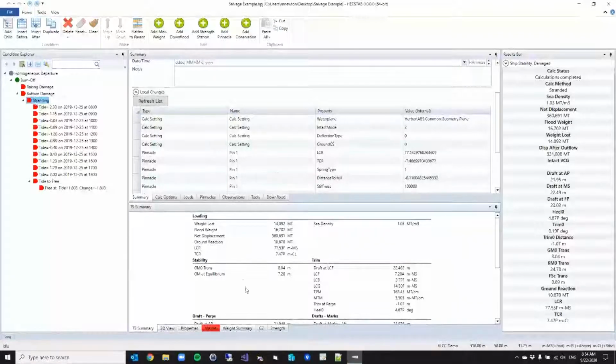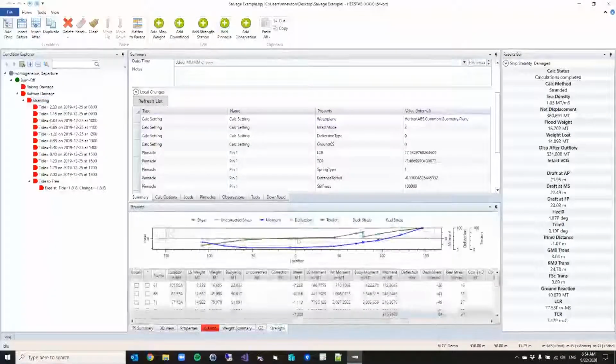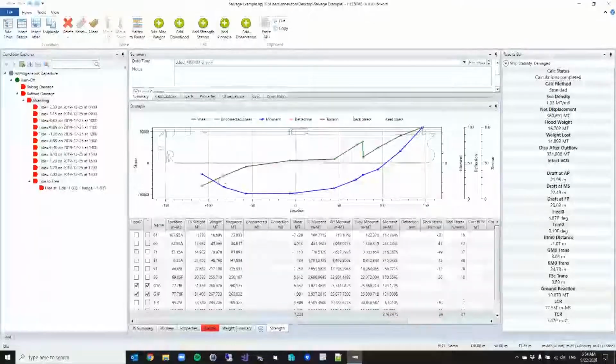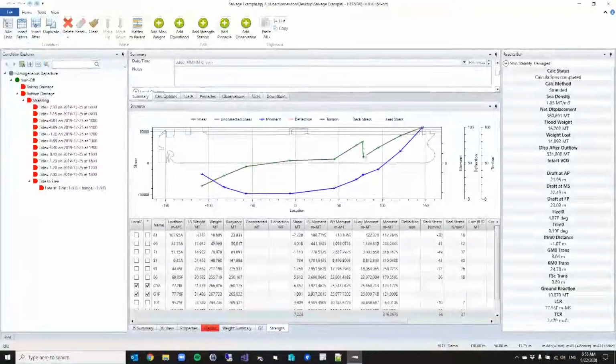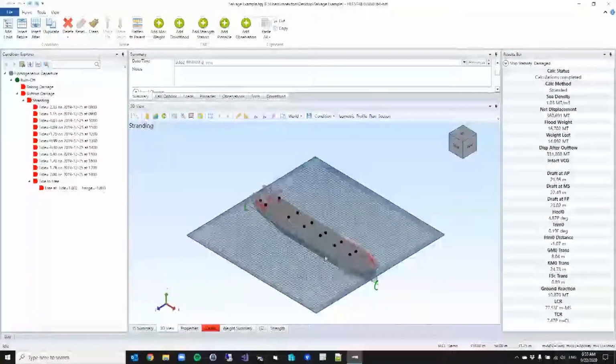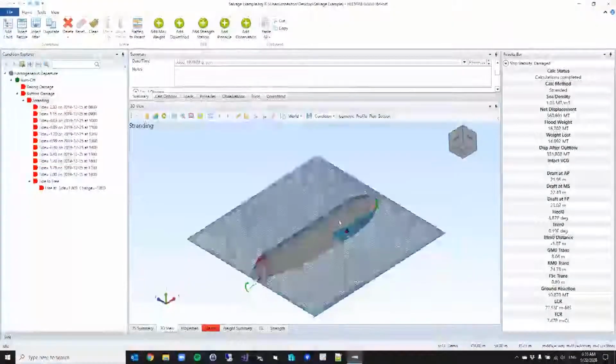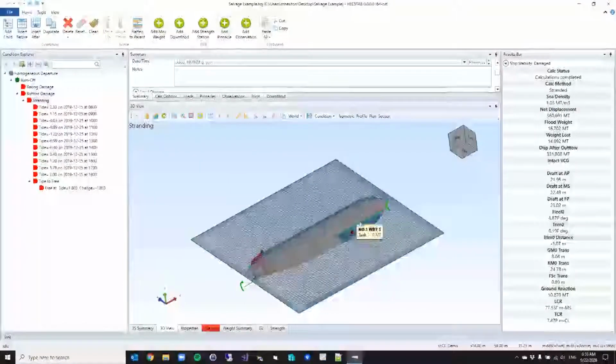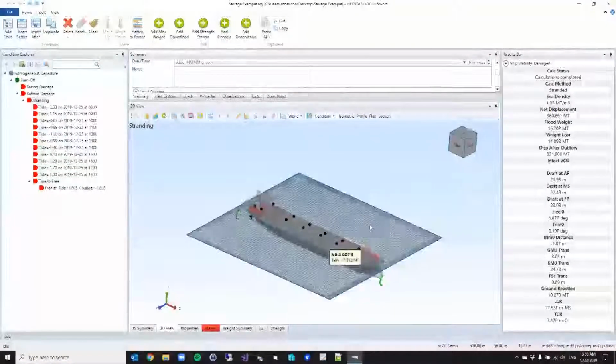So in this case, on the strength side, we can calculate what the force is at that location. You can see the corresponding strength and shear has a big gap here where the grounding has occurred. If I look here in my graphics, you can see that I've located the pinnacle in this location. So that's what's driving the calculation.